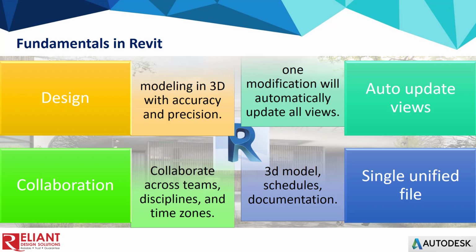It not only contains your building model, but also comes along with documentation such as schedules, for example, door schedules and column schedules. Revit can also do the same, including analysis reports and also sheets that have your floor plan, ceiling plan, section, and elevation views with the title block.